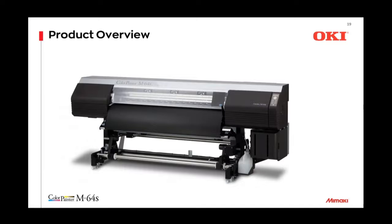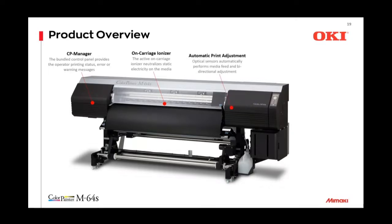All right, so here's the machine. We've spoken about the bundled CP Manager that provides warnings offline, which is great. Online ionizer, which is standard, great for this model. Automatic print adjust. This optical sensor automatically performs media feed and bidirectional adjustment. Exceptional feature. High-speed print heads, industrial print heads with the nozzle guard for better reliability. Automatic head washing. This is a really nice system. This is like a rotary type system where we actually wash and moisten the heads and wipe the heads all in the one system.